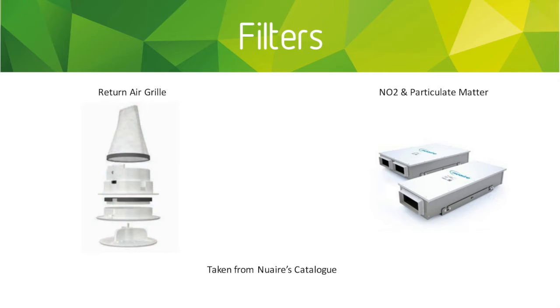Well, one of the main reasons people put in MVHR is to make sure you have good air quality. It also helps with external noise. So if you're living on a very busy road, you don't need to use your windows. You can also bring in air from a different source. You might have a very busy road on one side of your building and a very quiet area on the other side, so you can bring your supply air from that.